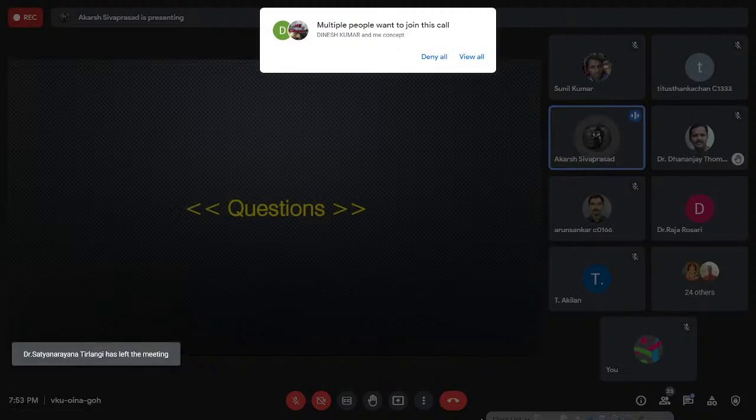Say if you want to make dental implants, dental surgical guides and invisible aligners, you can print hundreds of them at once rather than one each time. So if it's throughput, I would rank DLP. If it is the capital, I would rank FDM as the cheapest.